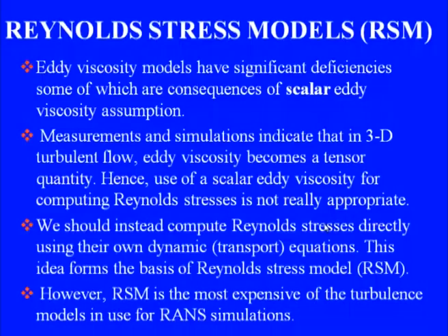So, we should instead now try to compute Reynolds stresses directly using their own dynamic or transport equations. This particular observation is what forms the basis of the Reynolds stress model, that is to say, let us derive the transport equation for Reynolds stresses and then try to solve them. But it is not as simple as it appears to be. First, it is one of the most expensive of turbulence models, and though we can derive the transport equation for Reynolds stresses starting from Navier-Stokes equations and the Reynolds averaging procedure, we will quickly realize that new terms appear which need to be modeled.